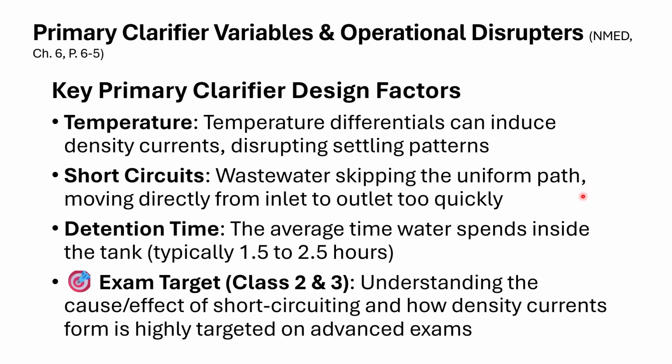And detention time: the average time that wastewater is going to spend in a clarifier, the primary clarifier, is 1.5 to 2.5 hours. That's for any sedimentation basin. Okay. For levels 2 and 3, particularly, you want to understand the cause and effect of short circuiting and how density currents form, because you're going to see some of those questions on your level 2 and level 3 exams. Okay.